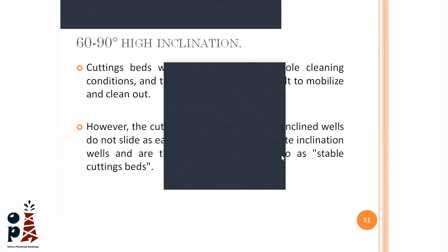Then we talked about the most important and the most critical function of drilling fluid, which is pressure control. We talked about the mud window, the hydrostatic pressure equation, and ECD for pore pressure or formation pressure, fracture pressure. We talked about the factors affecting hole cleaning, and hole cleaning in different sections of the well: vertical, intermediate inclination, and horizontal inclination. So guys, that will be all, and I'm trying to catch up with your questions quickly before giving the mic to my friend Isam.